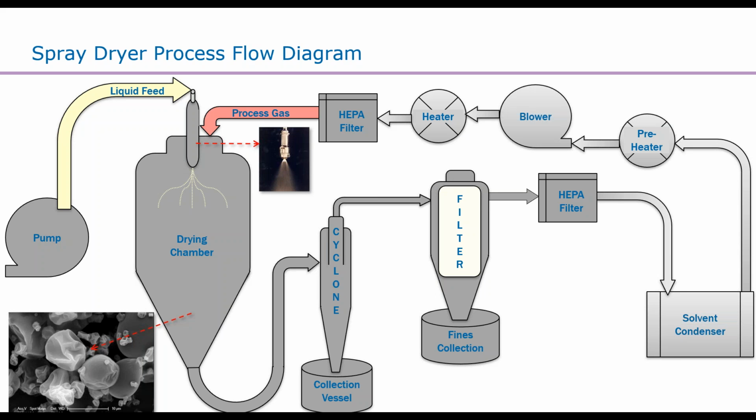It's important to note that though the process gas coming in is relatively hot and referred to as the inlet temperature, the vaporization requires a large amount of energy, meaning that the SDD particles are mostly experiencing a much lower temperature, normally referred to as the outlet temperature.